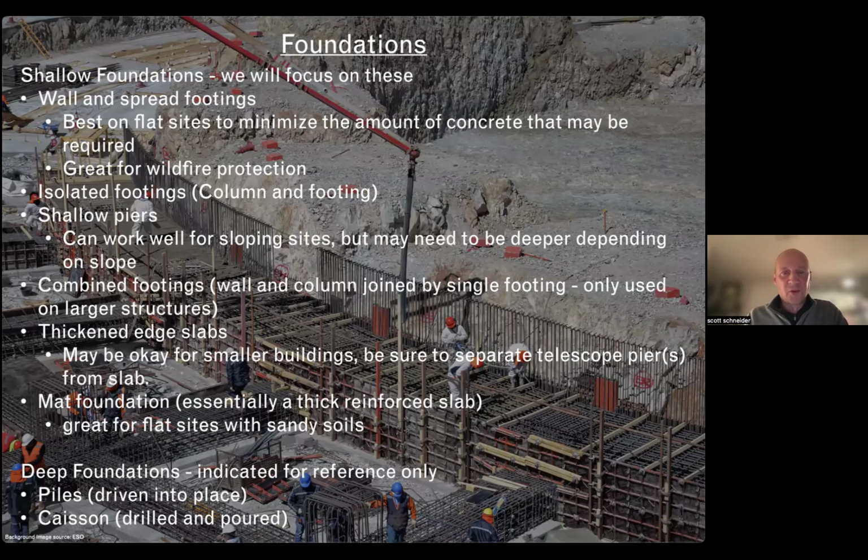But the foundations that we typically use would be the shallow kind, and we have wall and spread footings. You can use them on flat sites, and you can use them on slightly sloping hills. When the hills get too steep, you would probably want to switch to piers, because you'll end up using a lot more concrete and you don't need to spend money in that place.